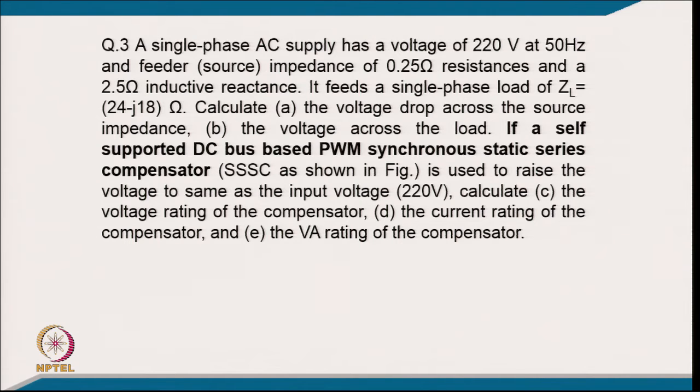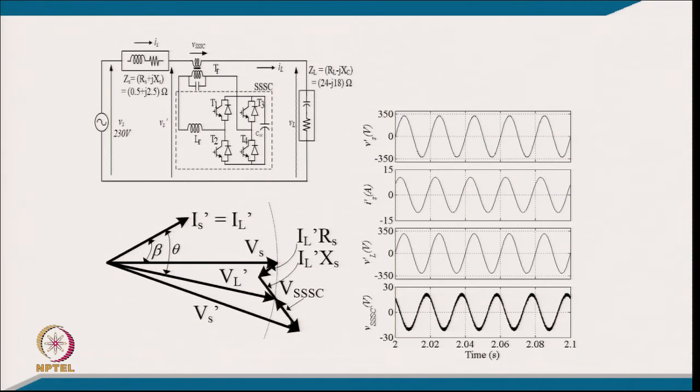If a series connected DC bus based synchronous static compensator is used to raise the voltage to the same as the input voltage of 220, calculate the voltage rating of the compensator, the current rating of the compensator, and the VA rating of the compensator.